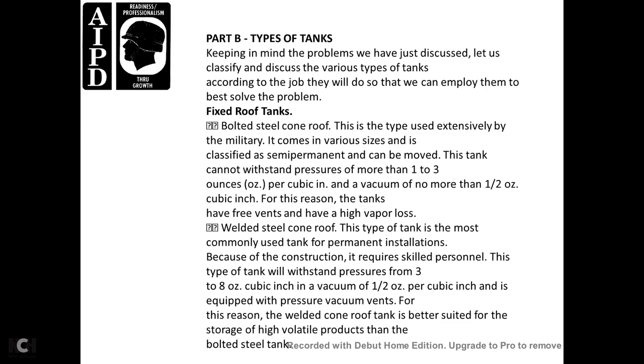This is the type used extensively in the military. It comes in various sizes and is classified as semi-permanent. It can be moved. The tank cannot withstand pressure of more than 1 to 3 ounces per square inch or vacuum of more than 1/2 ounce per square inch. For this reason, the tanks have free vents and have high vapor loss.